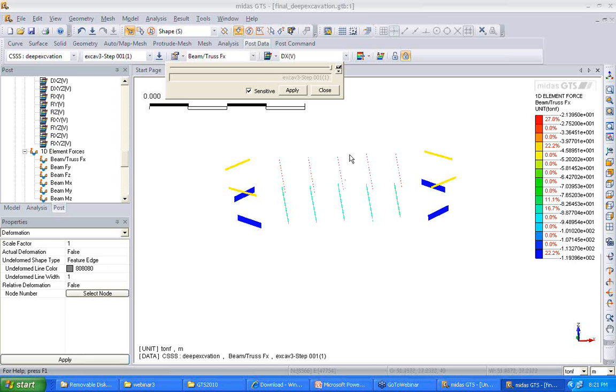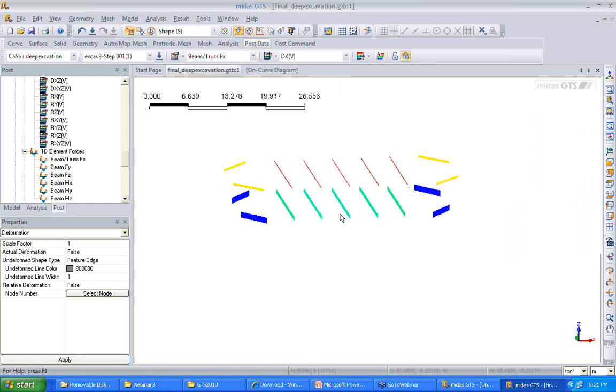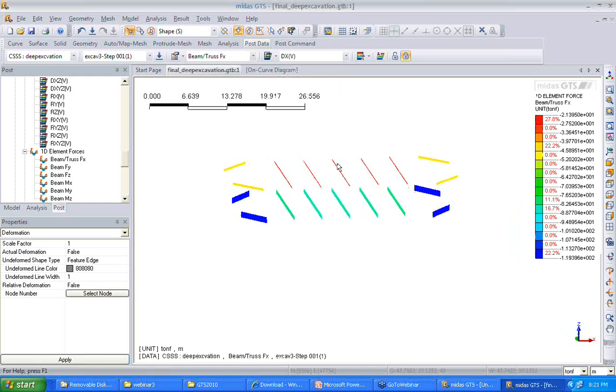So this is very important when we need to perform, as I previously said, a continuity analysis. The strength of the effect of one strut on the whole family of structure elements present in that excavated ground can be seen in that continuity analysis, in which you just remove a particular strut and then perform the analysis.